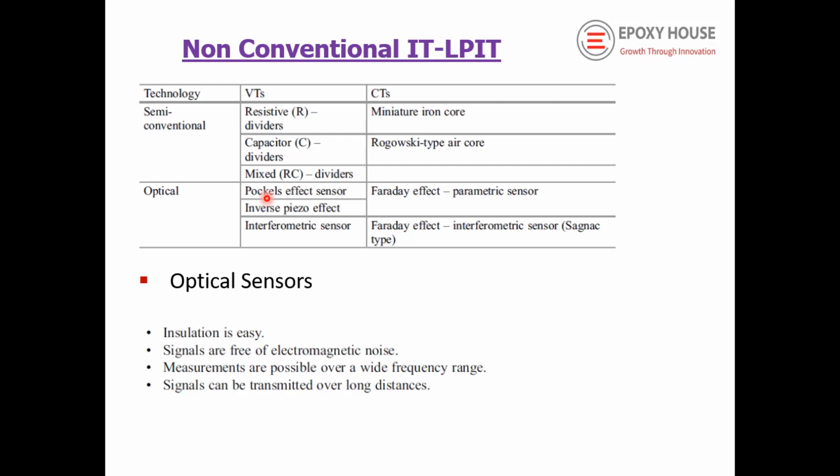For example, in the olden days people were using high voltage measurement by resistive divider. The same concept is used in most of the medium voltage switchgear, resistive voltage divider, and capacitive voltage divider. Capacitive voltage divider is also used in high voltage and low voltage both applications.